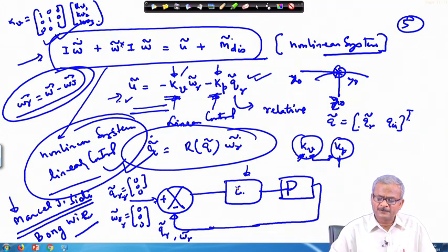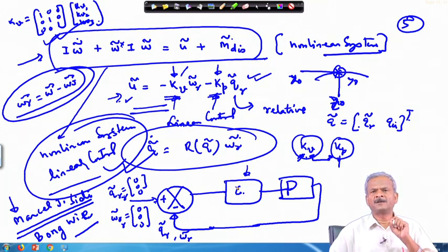Okay. If you are looking for the fine tuning of the control, means pointing the satellite inertially very precisely, in that case you need the micro thrusters. Using the normal thrusters it will not work. So, you require a very small amount of force or impulse, and the torque generated out of that will then be small, and you will be able to maneuver your satellite by a very small amount.